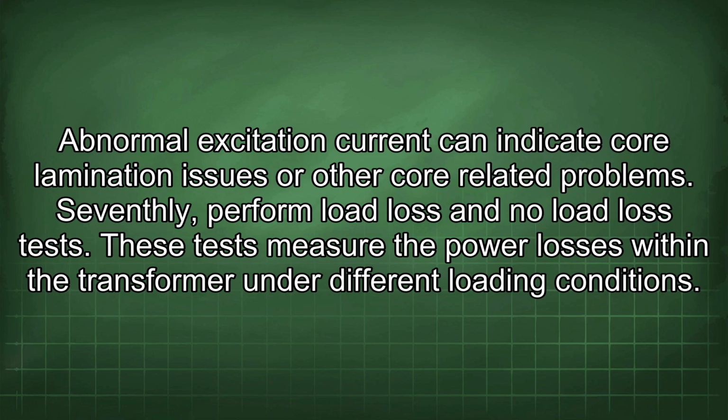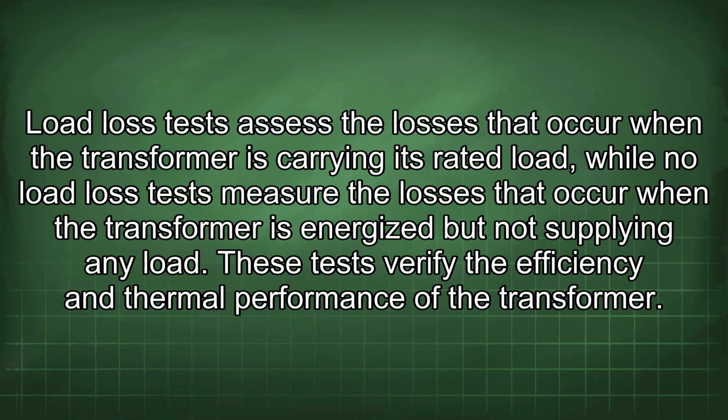Seventhly, perform load loss and no load loss tests. These tests measure the power losses within the transformer under different loading conditions. Load loss tests assess the losses that occur when the transformer is carrying its rated load, while no load loss tests measure the losses that occur when the transformer is energized but not supplying any load. These tests verify the efficiency and thermal performance of the transformer.